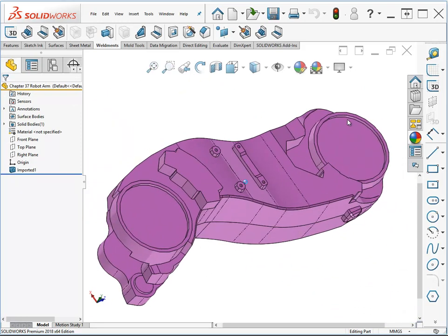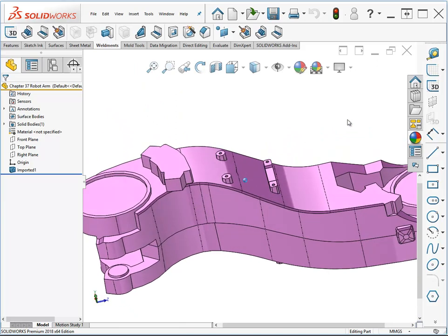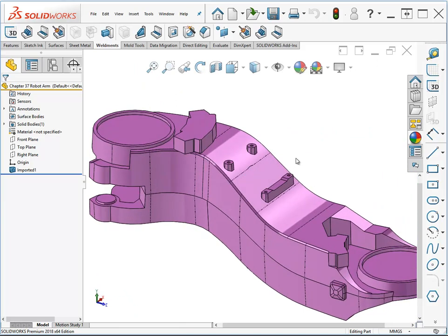Now, SolidWorks has what it calls direct edit tools. And direct edit is a method of editing a model without having a list of features on the side. It's the kind of modeling that Solid Edge synchronous technology does, and various other modelers are dedicated direct edit modelers. SolidWorks is not a direct edit. The opposite of direct edit is history-based modeling. Some people say it's parametric, but I know direct editors can be parametric as well.